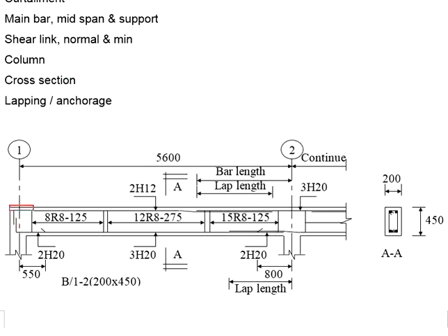The beam is supported by the column. When you show the column, you have to cross-check with the structural key plan the locations of the column as referred to the grid line. You need to know whether the grid line is at the center of the column or the grid line is at the edge of the column.